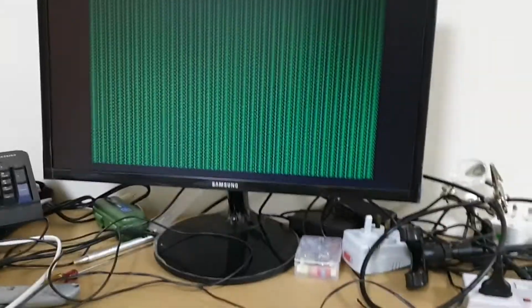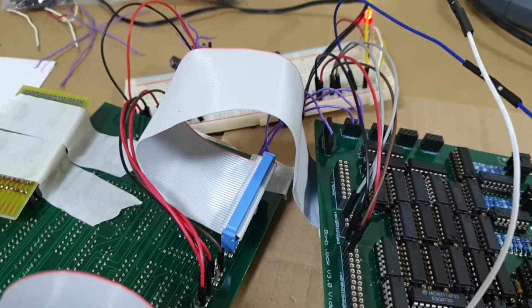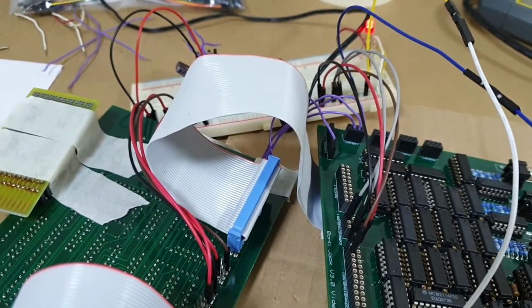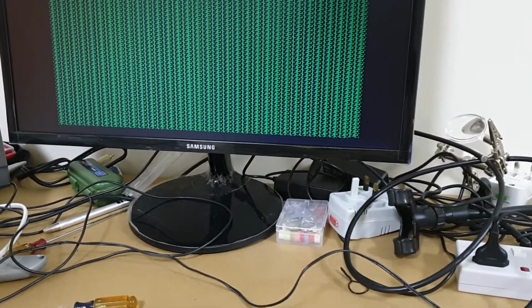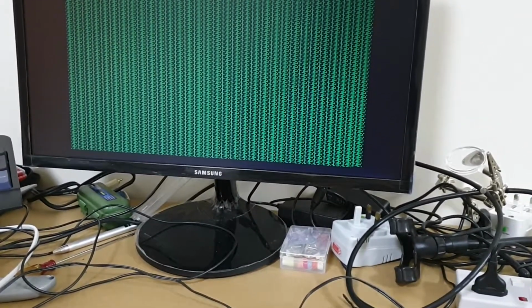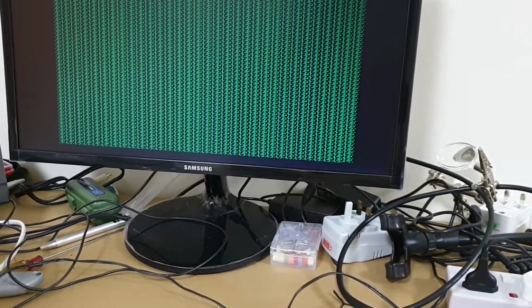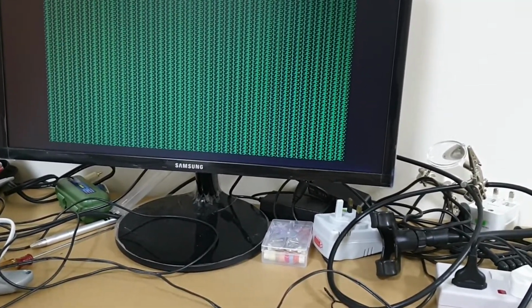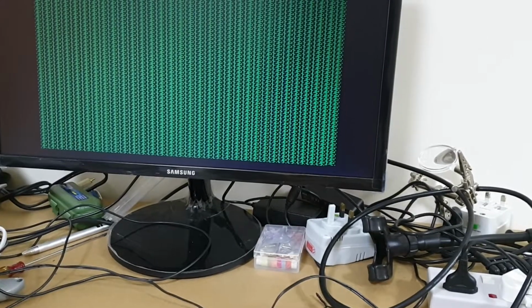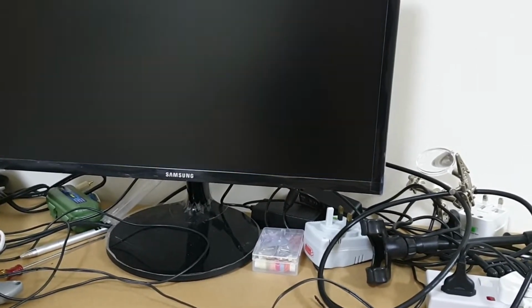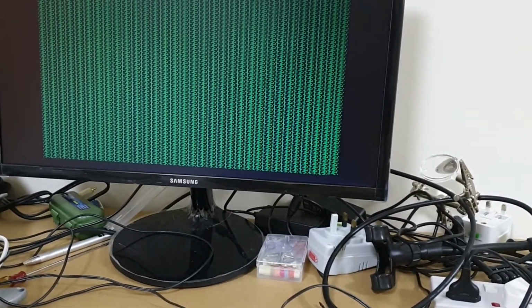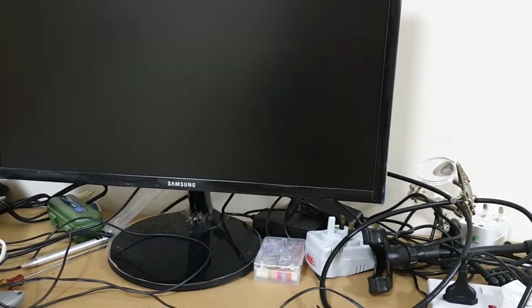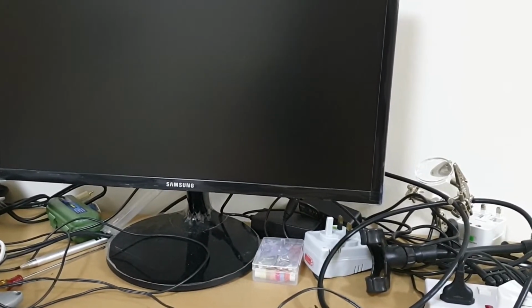So debugging progress update. This plug is not entirely seated on the header yet, and we can see that we're starting to see a repeated row of, I think that looks like 4 pixels, which means that the first 2 vertical lines on the row and column headers are connected. If I apply a little bit more pressure, the display has already blanked out when I put too much pressure on. If I put a little bit more pressure on, okay, that really is intriguing.